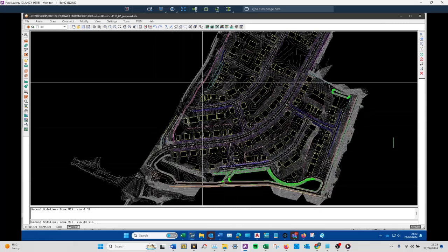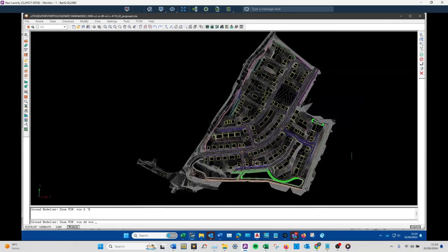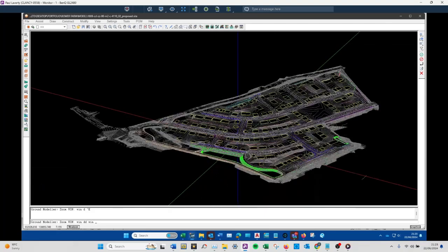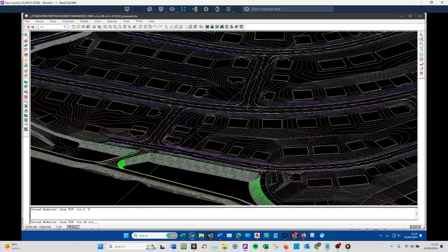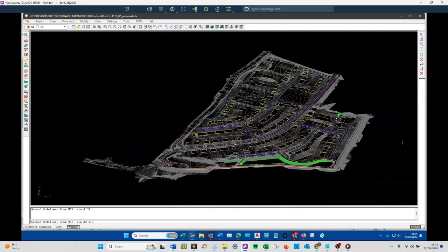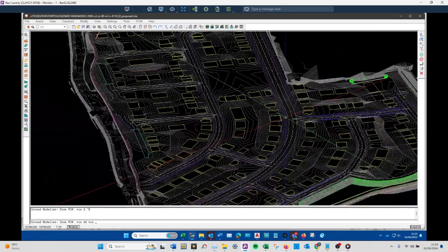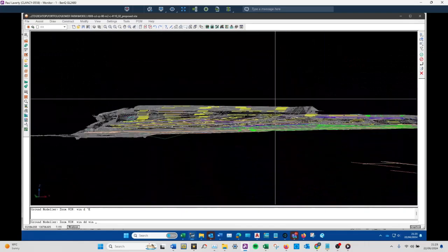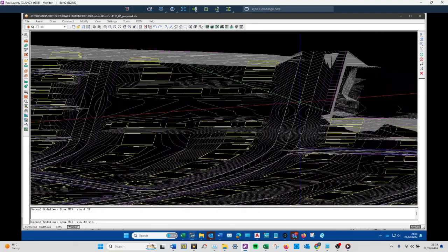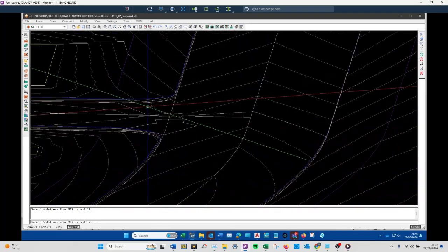Now you may be thinking that we went overboard with the use of roads for things like footpaths, and you could have done them as 3D lines or turning heads, but this gets into how you set up drawings, and there are different ways to do things. There are some people I know that do retaining walls as roads purely for the setting of aspects, so it really comes down to personal preference as you learn PDS and decide how you want to set things up.